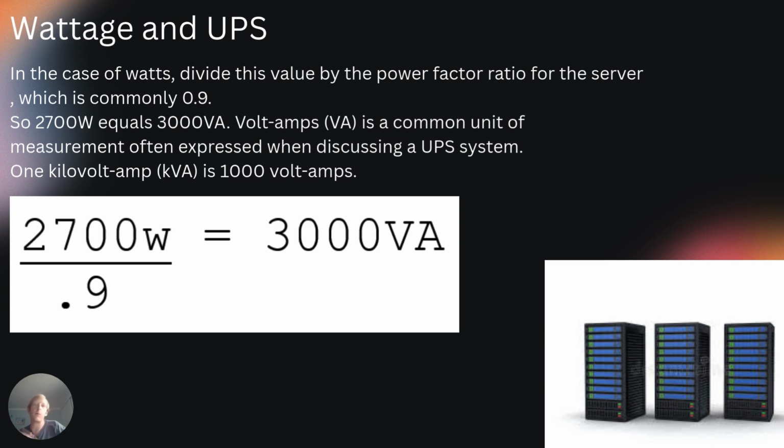Okay, here's an example. I'm going to turn this into a PBQ in the future. But yeah, you'll need to know power. You'll need to know how to do a formula, how to calculate your servers, your power consumption, get the load on a UPS, make sure your clients and customers are happy. So I'm going to give you this example.